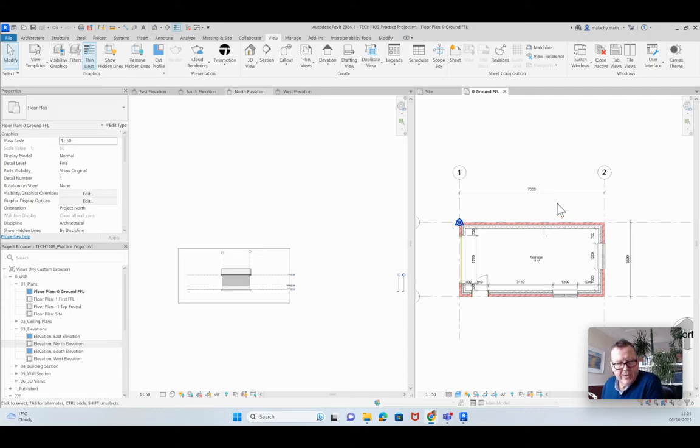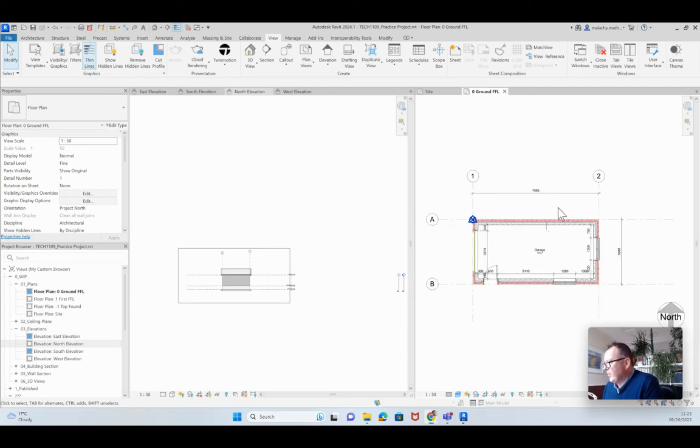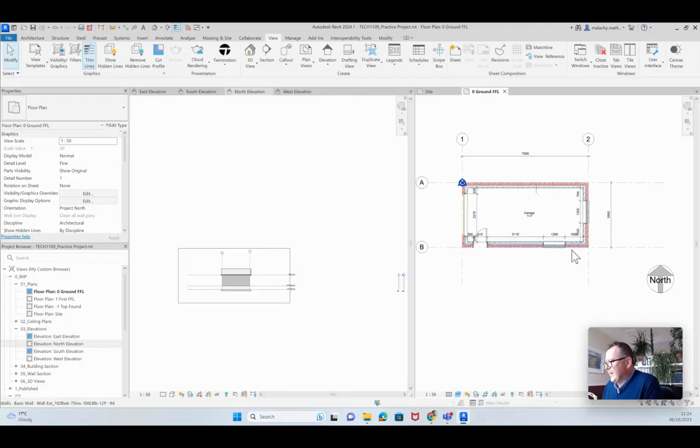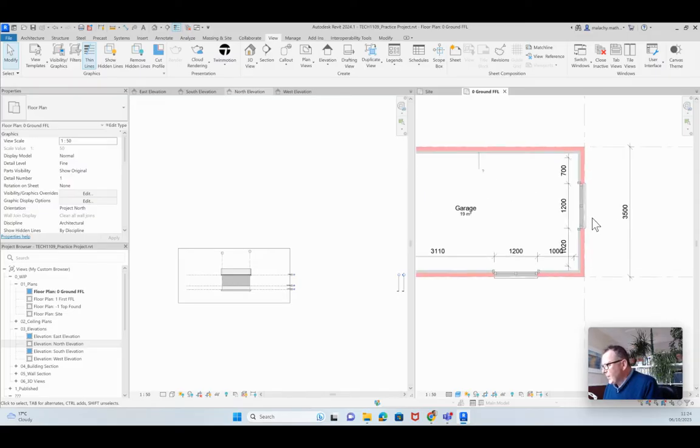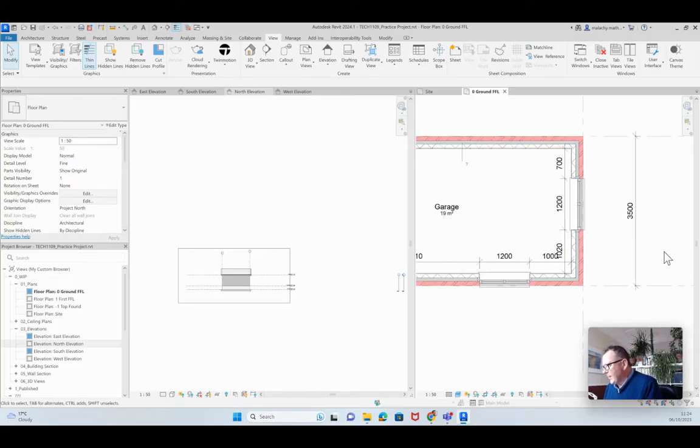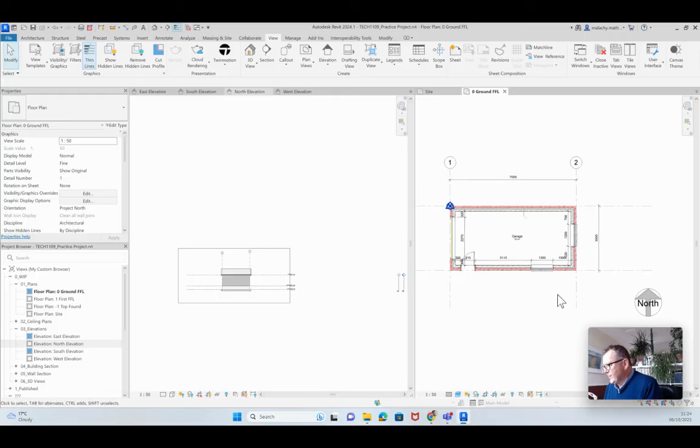Now, students, we'll continue on part 7. What we were working on this morning is that we're going to extend the garage in order to put in a little WC, wash hand basin and a shower. So I'm going to take this wall and extend it out a certain distance. Normally you'd want around 1200 to 1350 width to get a decent shower and WC in.